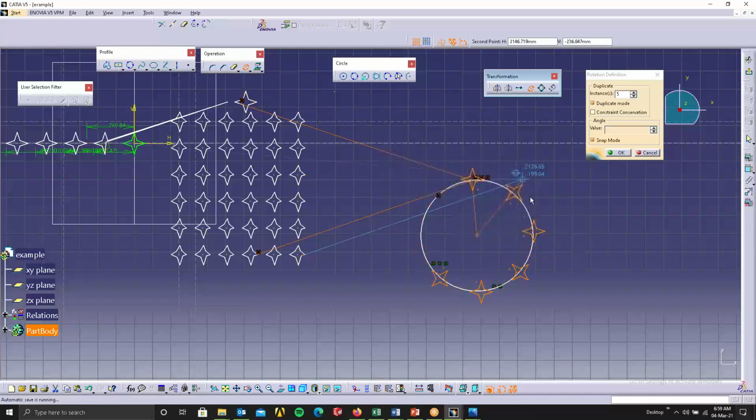Now I want to make these things sit at an equidistant angle. I don't want them to sit at a random angle. So how do I give my angle? I would have to divide and do all these things, right? It's an unnecessary waste of time. So what I can do is straight away enter 360 divided by the total number of objects.